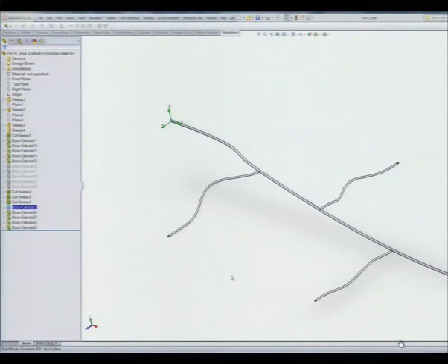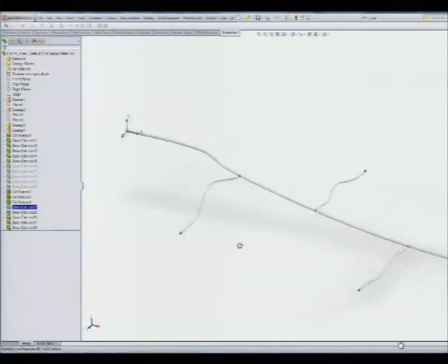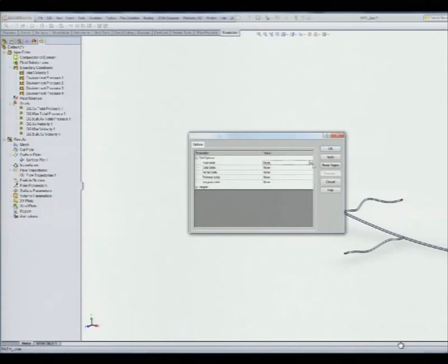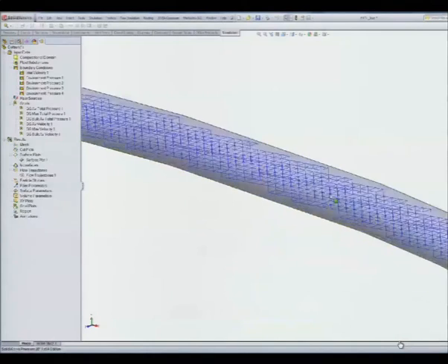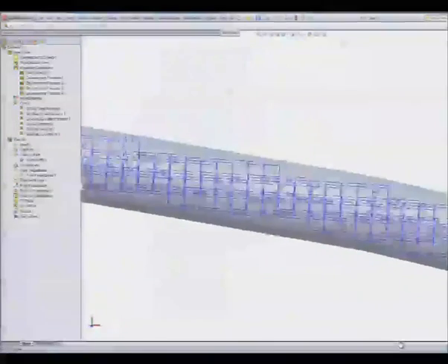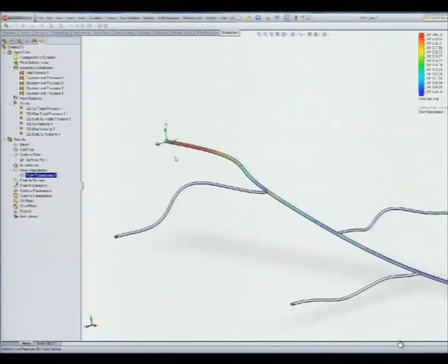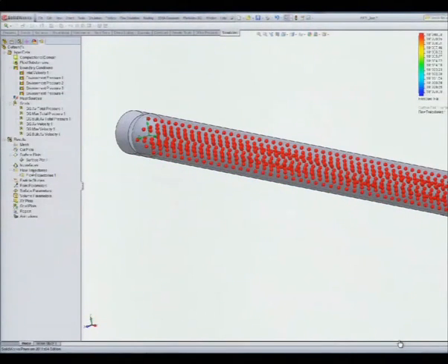So in this case, the challenges were two. First of all, the size, and the second challenge was the quantity of degrees of freedom of the flow. This is a flow simulation. What the customer wants to have is the pressure losses in every branch, and the forces active, because you may know that with flow simulation we can get the actual forces acting on the accessories.